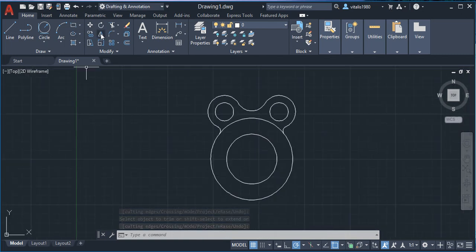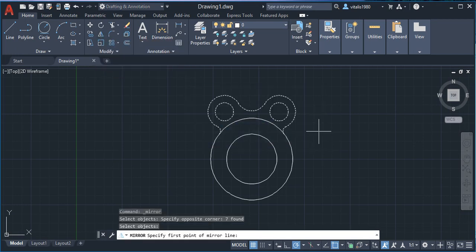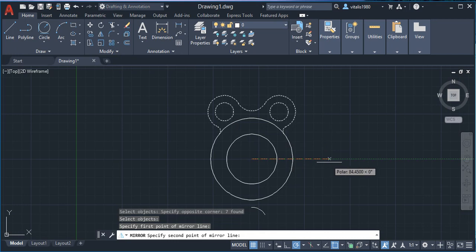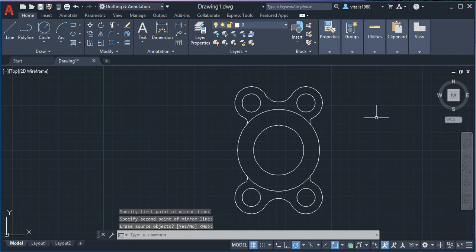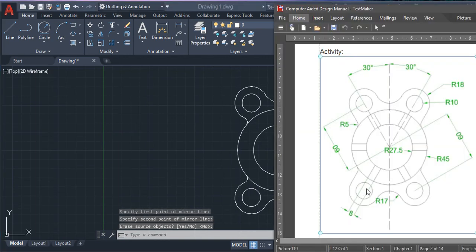I still need to do one more mirror. I'll select all of this using window selection, and then mirror across the middle. So you can see the only thing remaining are these lines that are here, and you can see we have radial symmetry with those pairs of lines, and we have 6 of them. So we can use polar array to create this object.